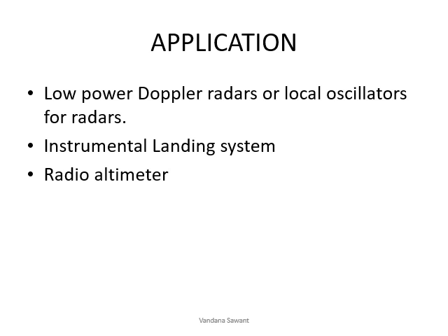Basically, it is to find out the distance of an object from the ground layer. This radio altimeter is used, and it always requires that the radio altimeter must be a compact device. So to have this compact device, a compact generator is also used. That is the Trapatt diode.